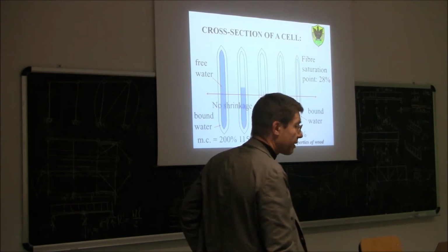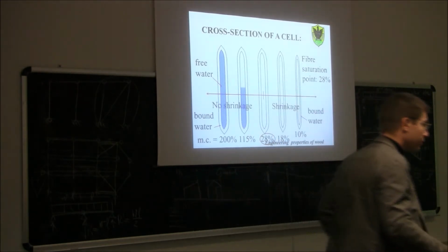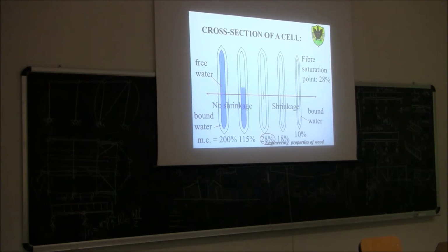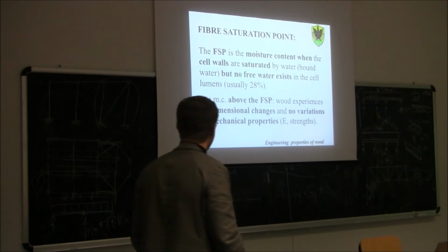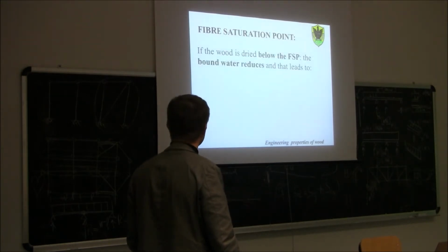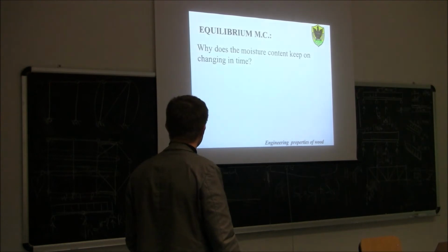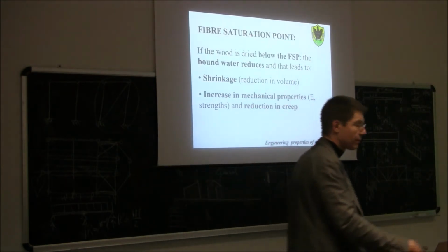Good. Another important remark. The mechanical properties of wood, so we said the stiffness coefficient, the modulus of elasticity, and strength, are not affected by moisture content above the fiber saturation point. So whether you have 15% or 100%, the strength doesn't change. Instead, below the fiber saturation point, the lower the moisture content, the better the mechanical properties. So basically, this is just a summary of what we have just said.